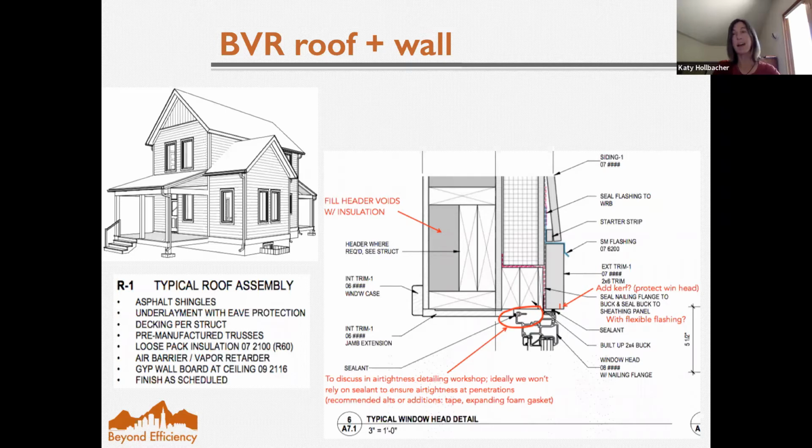Again, a goal had been foam free, but it's just really difficult to justify the cost on a project like this that has such high aspirations and otherwise has, every project has its budget challenges. So this is a nail-based 3.5-inch EPS, and it's going to end up being a really good end result with a fraction of the heating related energy use that a code level building would have seen.